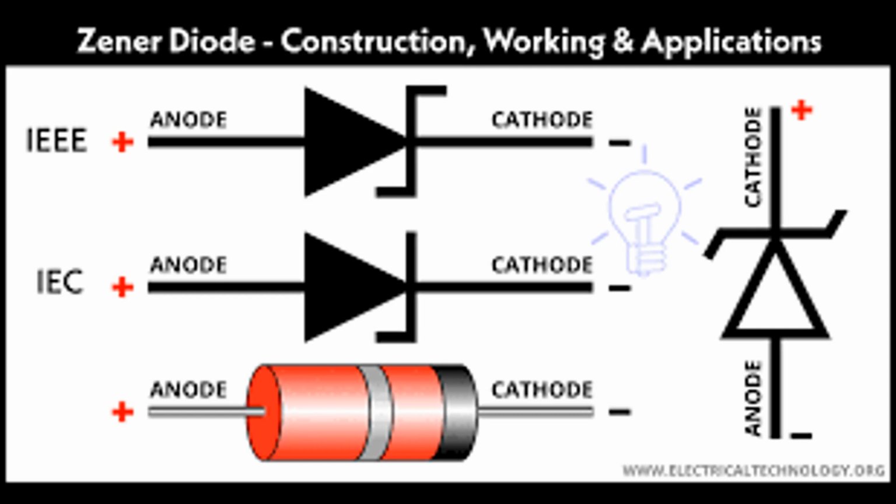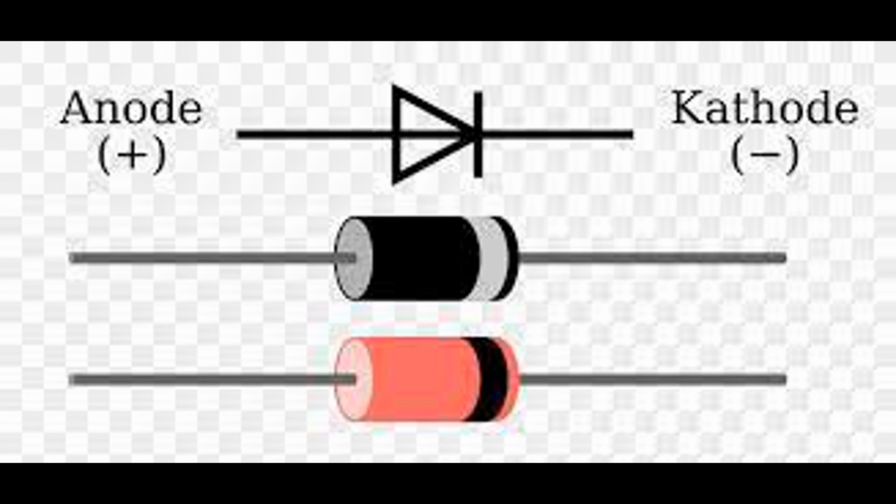Output. The output of the envelope detector is a waveform that represents the original information signal, which can then be further processed or sent to a speaker for audio reproduction. Applications. AM demodulation is used in AM radio receivers and communication systems. Diode-based envelope detectors are particularly effective in recovering audio signals from AM radio broadcasts.